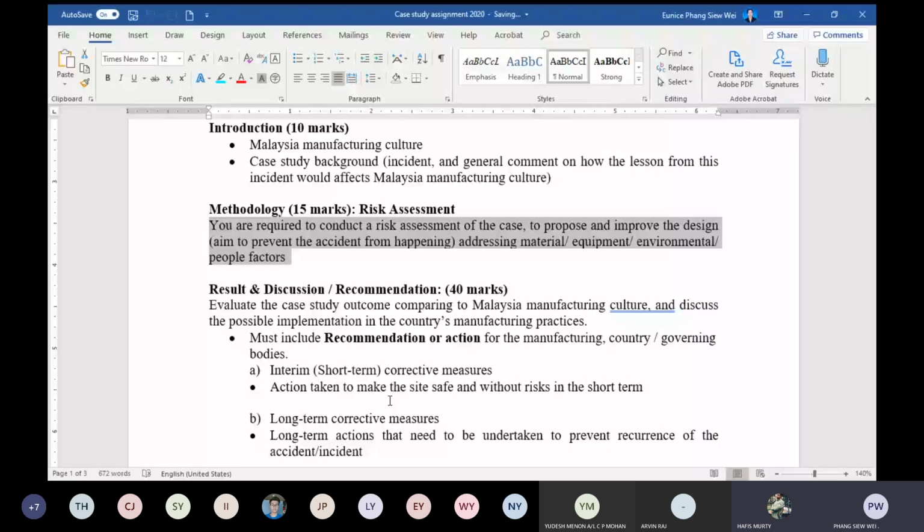But Miss, if I just use HAZOP, it's fine, right? Yes, it's still applicable. Of course, it's always applicable. That's why in safety, what I'm teaching all of you here is the tools, different types of tools. You can use this, you can use this, you can use this to calculate certain things or to assess certain things. So later, in another 2 weeks' time, I'm going to share on the event tree and fault tree analysis. That's also something you can use. That's very simple, but for that one you may need to get some data, because you need to know the fault rate of each of the elements that you look at.